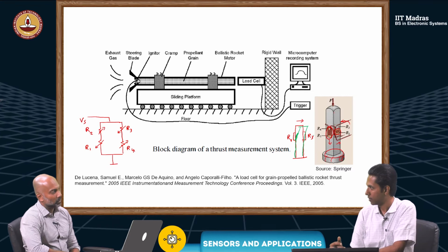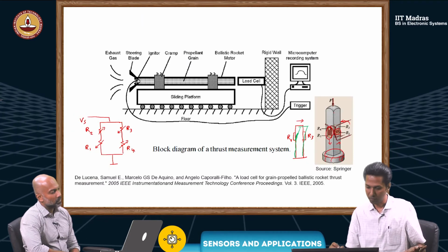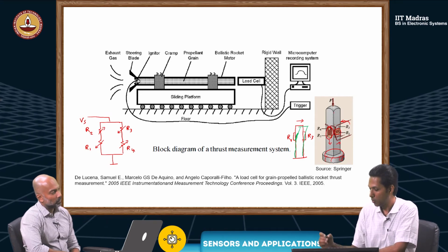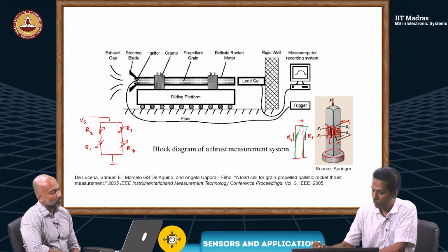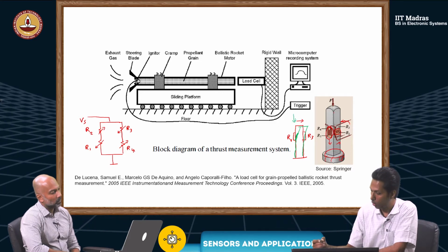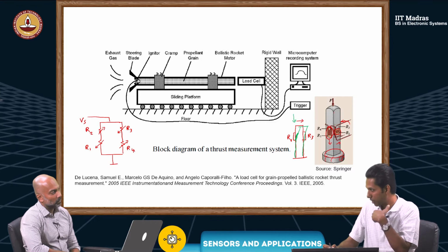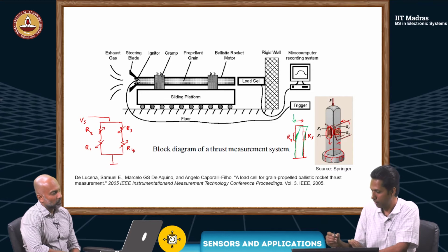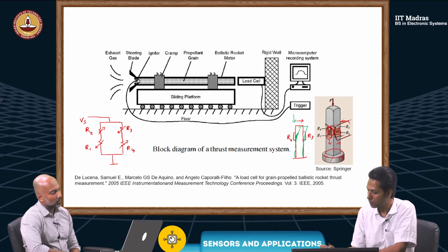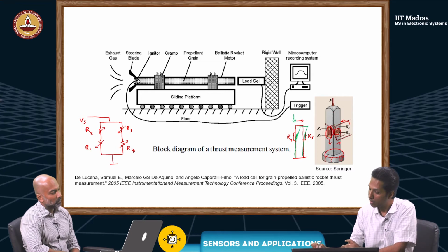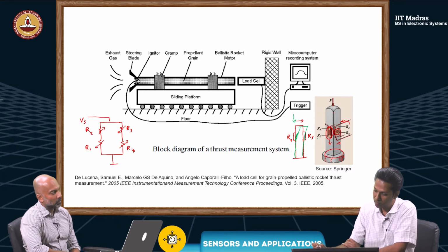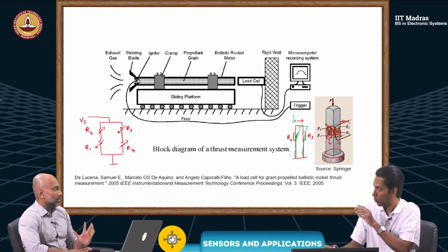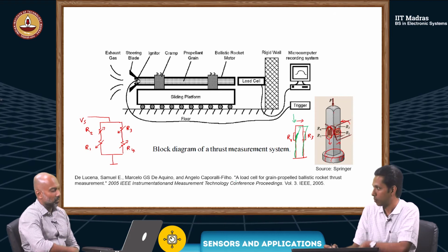That gets compressed, yes. So there is some unwanted effect here. What we were looking at was the force in this direction alone. We were not expecting a bend like this. But because the input force has a component in the horizontal direction, there is a bend, and that alters R1 and R3 in a different way than we were expecting, in addition to the original force component.